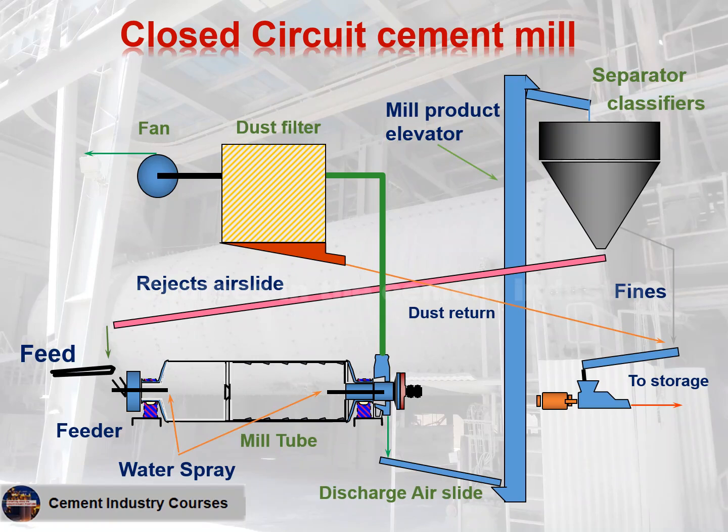1. Grinding capacity increases. 2. Grain size distribution of refined powder becomes sharp. 3. Refined powder temperature is reduced. 4. Power consumption rate decreases. 5. The abrasion of liners and balls is suppressed. 6. Grain size distribution of products can be adjusted by changing the circulation ratio and the classifier's run status.